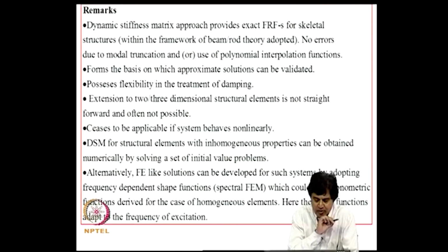The dynamic stiffness matrix approach provides exact frequency response functions for skeletal structures, that is, within the framework of the beam and rod theories that we adopt. No errors due to modal truncation or polynomial interpolation functions occur in these calculations. Therefore, these solutions can form a basis on which approximate solutions can be validated. That is the use that I perceive in the context of a finite element course. Now, it has great flexibility in treatment of damping, and that again adds to its value.